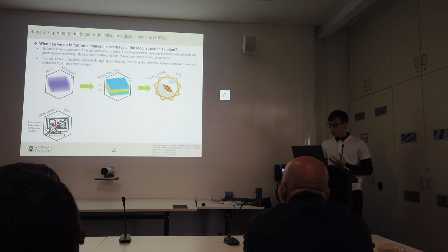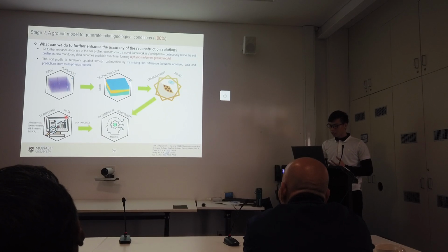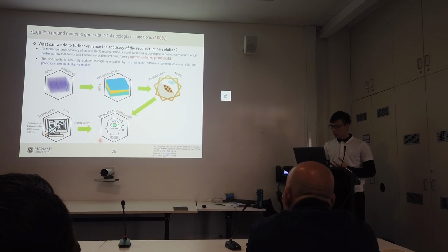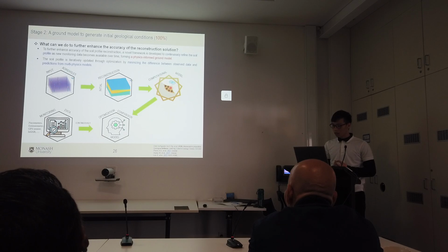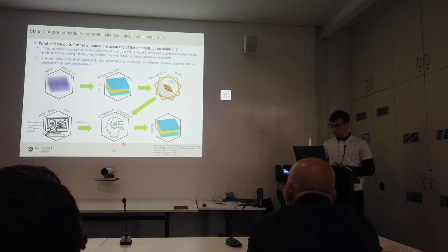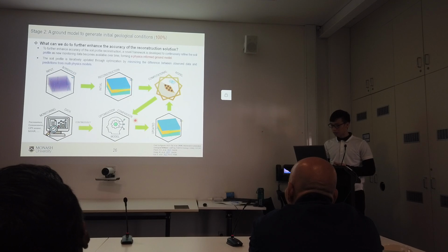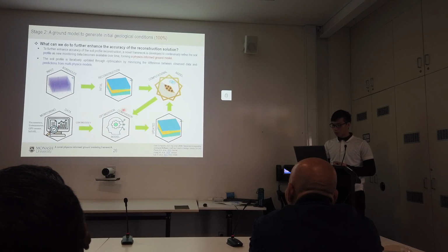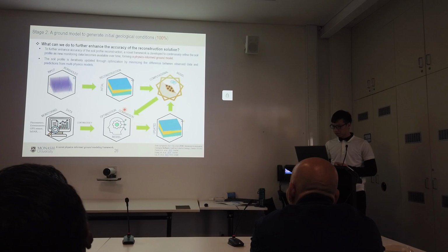At the same time, we have monitoring data from the field, for example from piezometers to measure water pressure. The key idea here is to use an optimization algorithm to minimize the difference between the numerical prediction and the monitoring data, so we can update the ground model. This updated ground model is then input again to the numerical model, allowing continuous refinement. This is the entire picture of our proposed framework, which relies on an effective optimization algorithm.